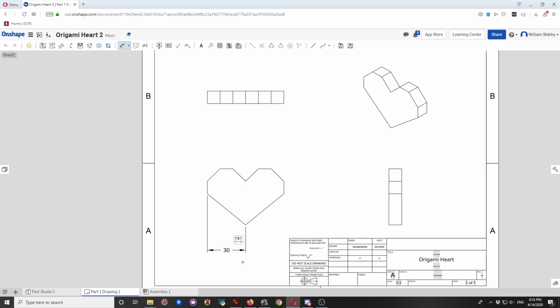Well, I thought I set it to be 3. Well, in our drawing, we're using centimeters as our units. We set 3 centimeters in our sketch. In our drawing files, the standard is using millimeters. So 30 millimeters is 3 centimeters. Easy peasy. So all of our numbers in here are going to be multiplied by 10.